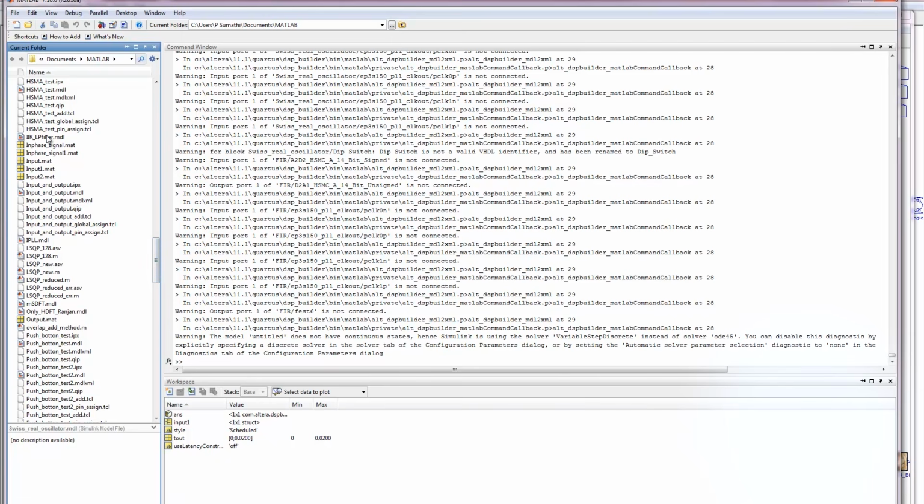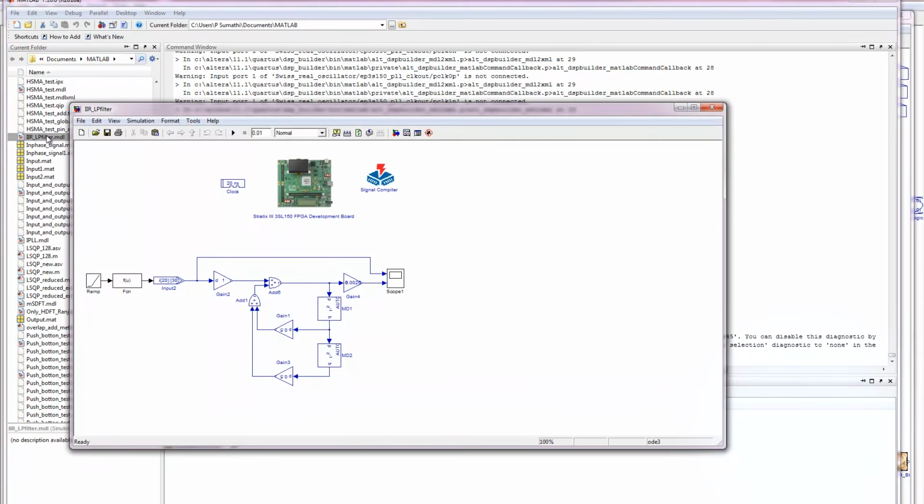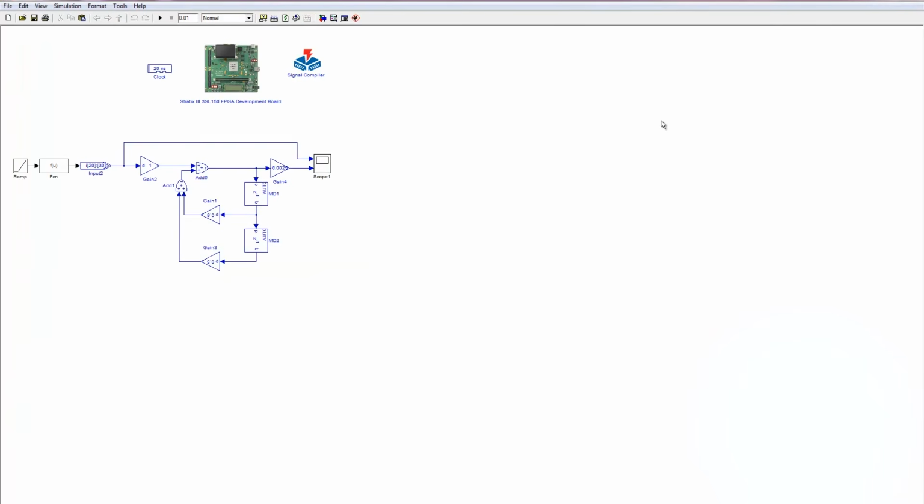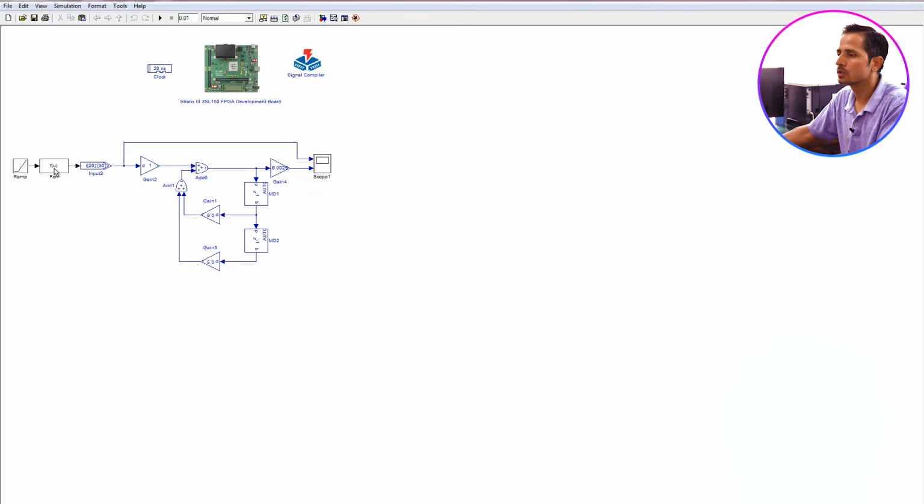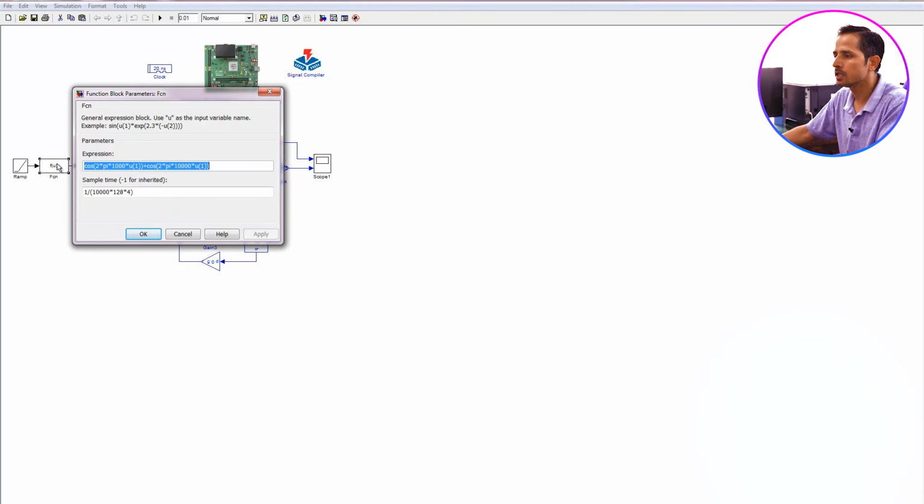This is the IIR low pass filter program. We can see here the blue boxes along with black boxes are also used. If this program is not directly synthesizable on the FPGA, I have to remove this black box if I go for hardware implementation. But here I am only showing the simulation. The input which I am giving is a combination of two frequencies.